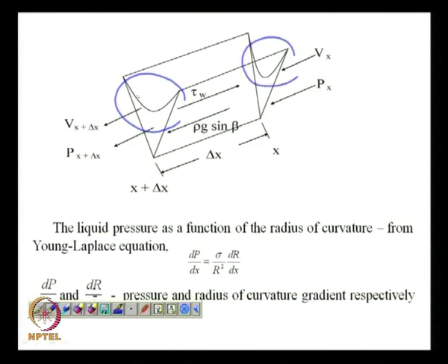So, let us say this is the cooler side, this is the hot side, this is the delta x, that is the control volume size, and I have flow whichever way; V could be negative. In this figure it is shown as if I have flow from the hot side to the cold side. Basically, the value of V that you are going to get out of it should be negative.